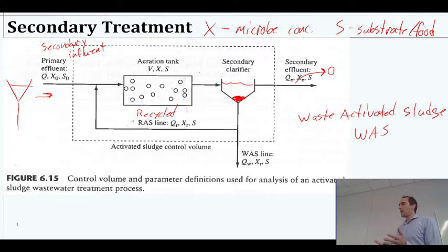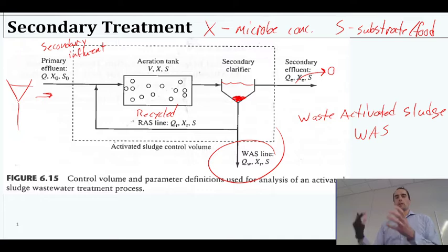it depends a little bit on what you want to do with it, because there's typically a lot of nutrients there that could be recycled. So you can take the sludge here that you decide to send to waste. Either way, you're going to dewater it, so you're going to squeeze out the nasty juices. That'll just be sent back into the beginning of the wastewater treatment plant.